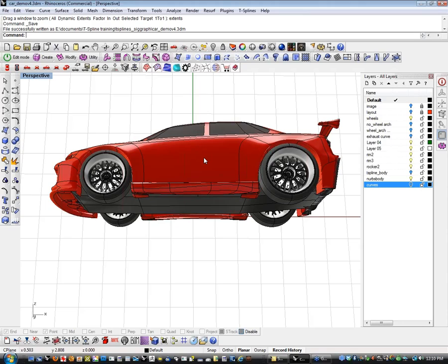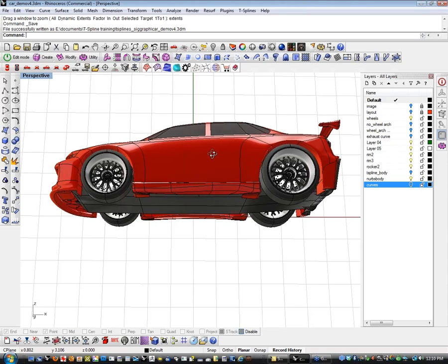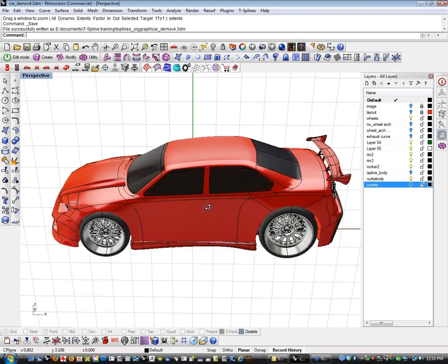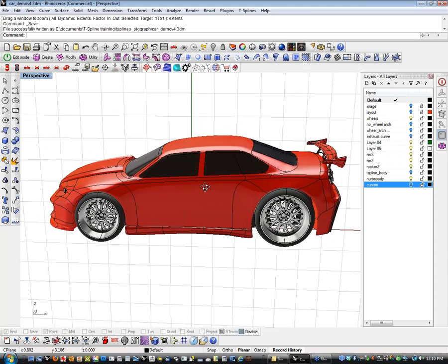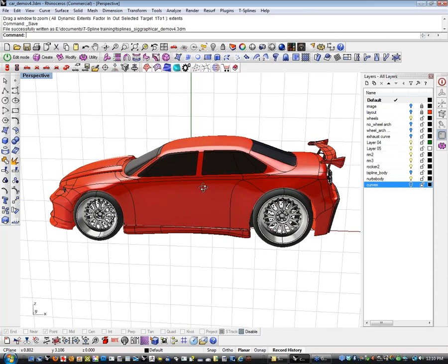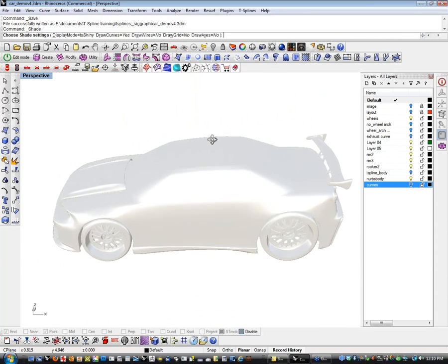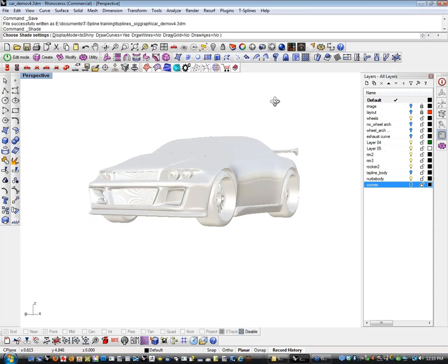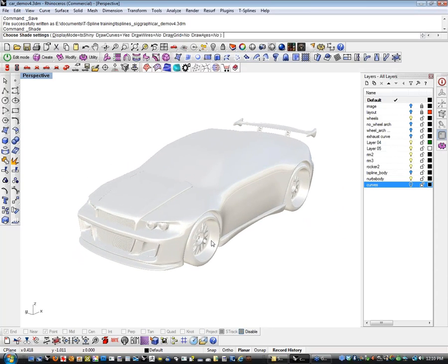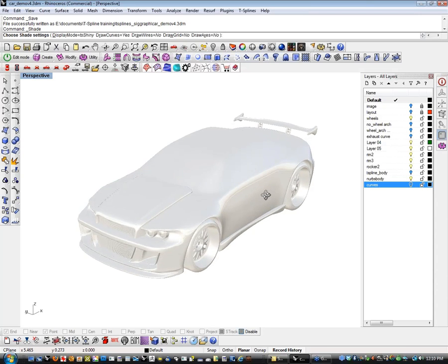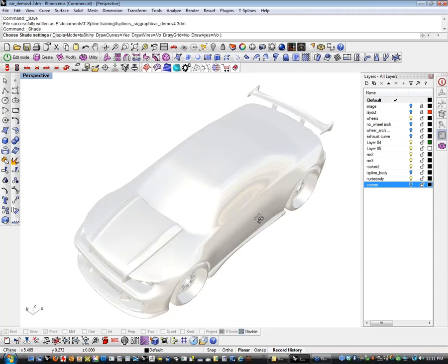That is something that consumes a considerable amount of time, and there are people who essentially specialize in Class A modeling, these particular aspects of the car. The other one, and let me shut the ISO curves off here real quick so we can look at this without any distraction. So basically, getting the shoulder highlight to track through the car is very difficult in NURBS,